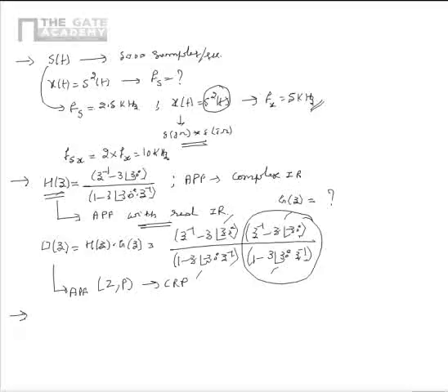Now let us consider another problem, as per which there is a signal g(t) given as cos²(200πt) multiplied by cos(800πt). We need to find the Nyquist sampling rate of g(t). We know that the signal g(t) can be simplified as half multiplied by 2 cos(800πt) cos(200πt).